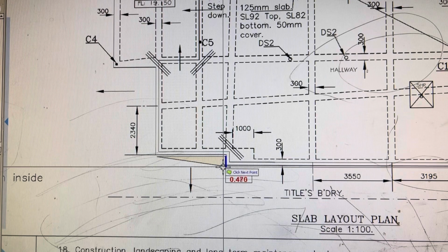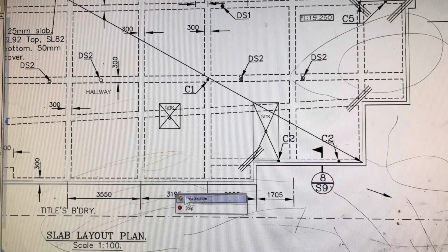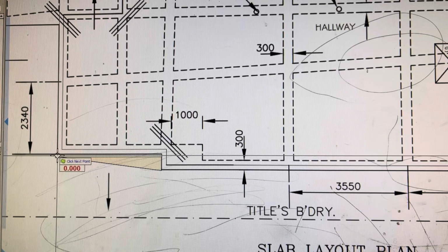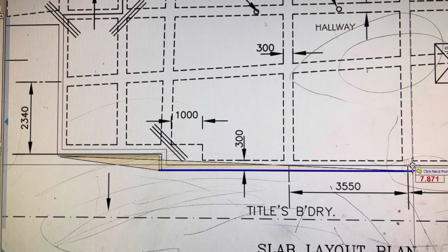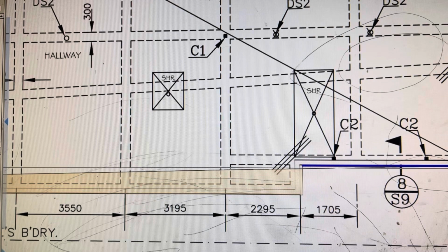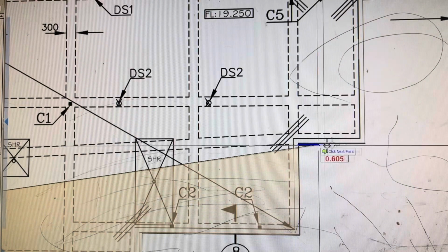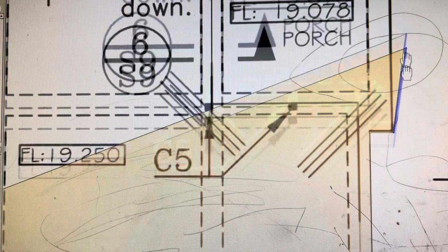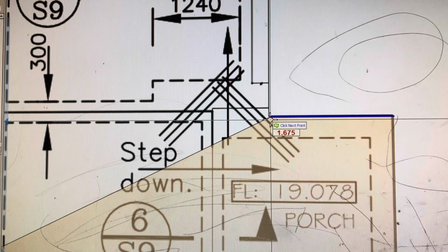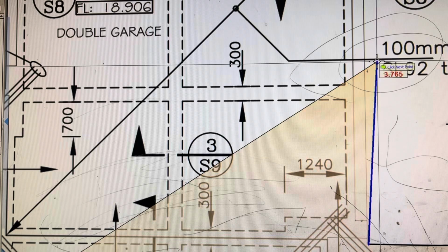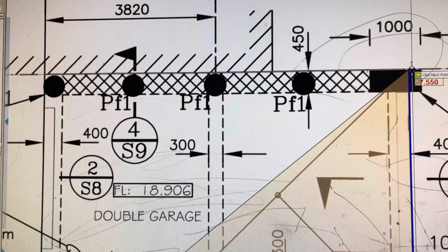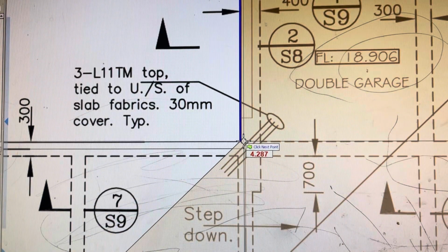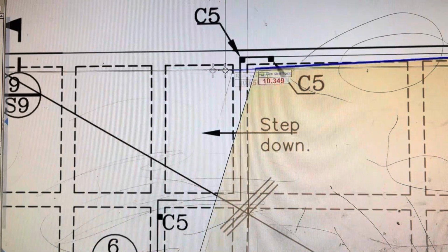So we are doing the takeoff of the area of the plan of this. Click all the edges to get the complete total area of the slab. With this digital software, you click on the points to get the accurate area of any element like slab, wall, roof, and the like.